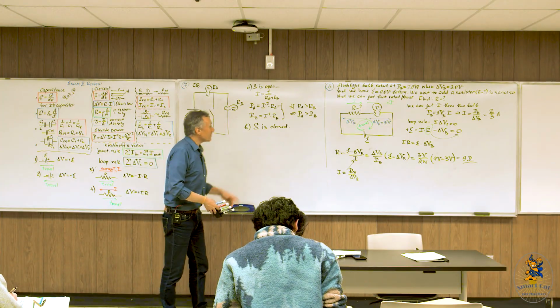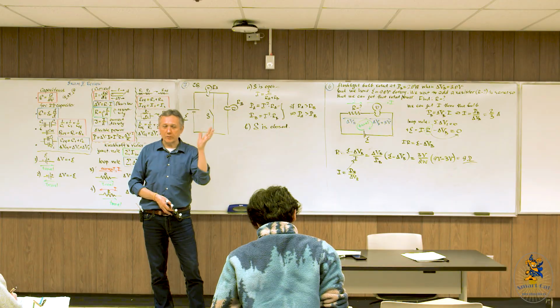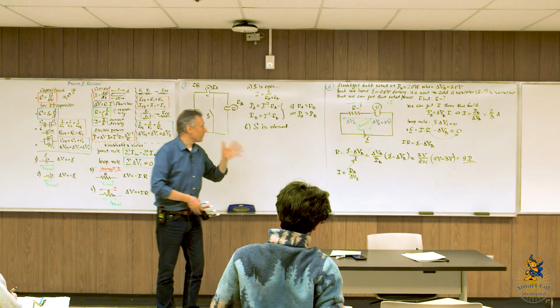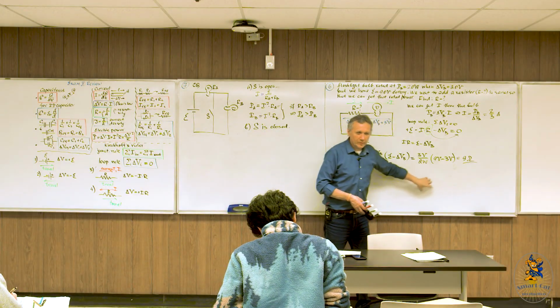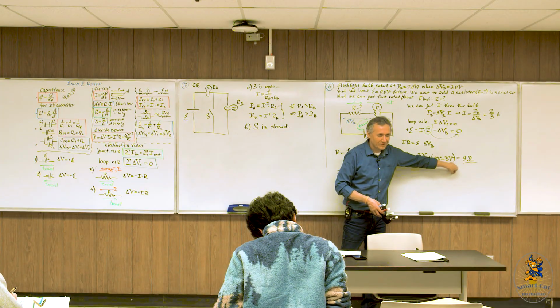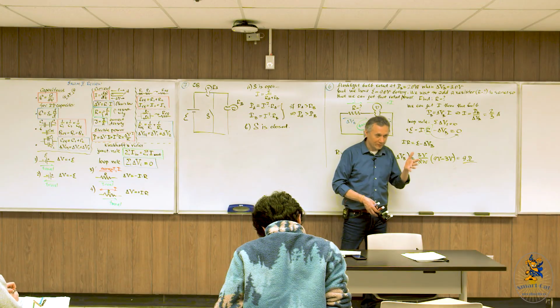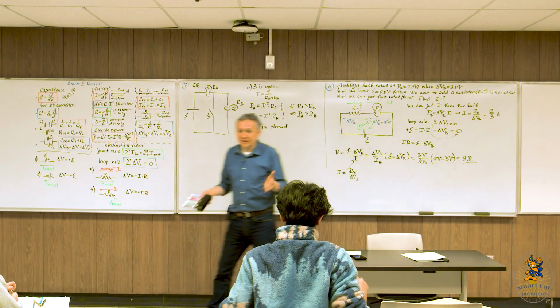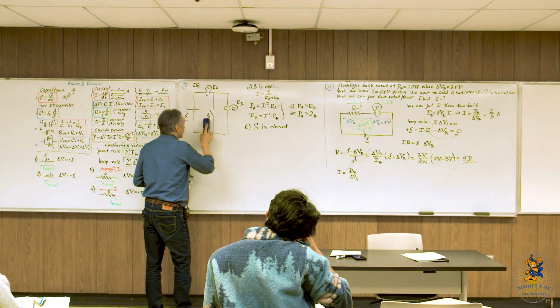Okay, you remember we discussed today at least once, maybe more, when we tried to find the equivalent resistance of those, like 3 or 2 resistors, and there was a wire going across. So what was the equivalent resistance? 0, right? So now it's sort of similar here. Look, now we close this switch.